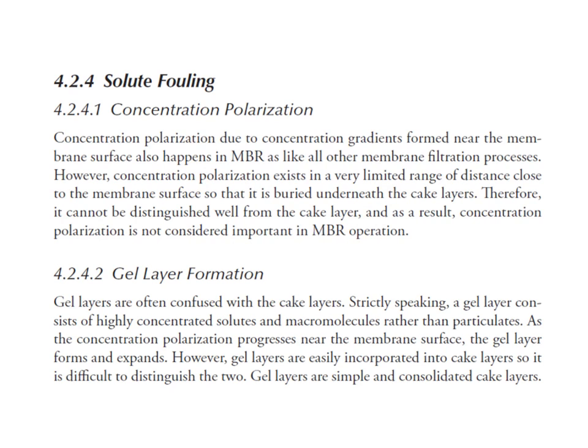When we look at this solid fouling, there are a couple of things that we have to consider. The first one is concentration polarization. Concentration polarization is due to a concentration gradient formed near the membrane surface, and it also happens in MBR as in all the other membrane filtration processes. However, in MBR systems, concentration polarization exists in a very, very small range of distance, very close to the membrane surface.